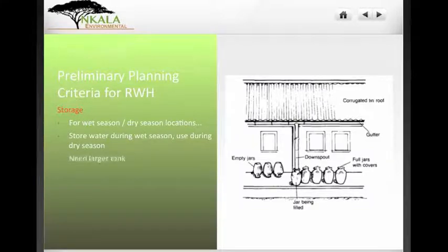What that means, of course, is that you need a larger tank. So if for our previous example you weren't in an area that had an even distribution of rainfall, then that 2.5 cubic meter or 3 cubic meter tank would not be sufficient for your needs, because water is not going to be steady like that.